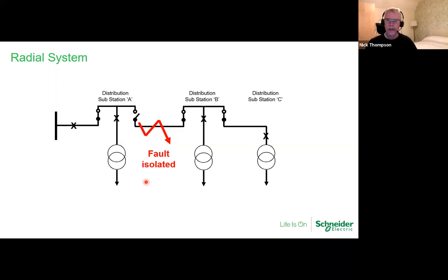So substation A, right-hand side, right-hand ring switch is now open or off. And in most ring main units, the switch is also rated to be a disconnector as well. So it's got a much larger gap inside the tank. Operationally, that will allow us to safely close the circuit breaker and then put customers back on supply.